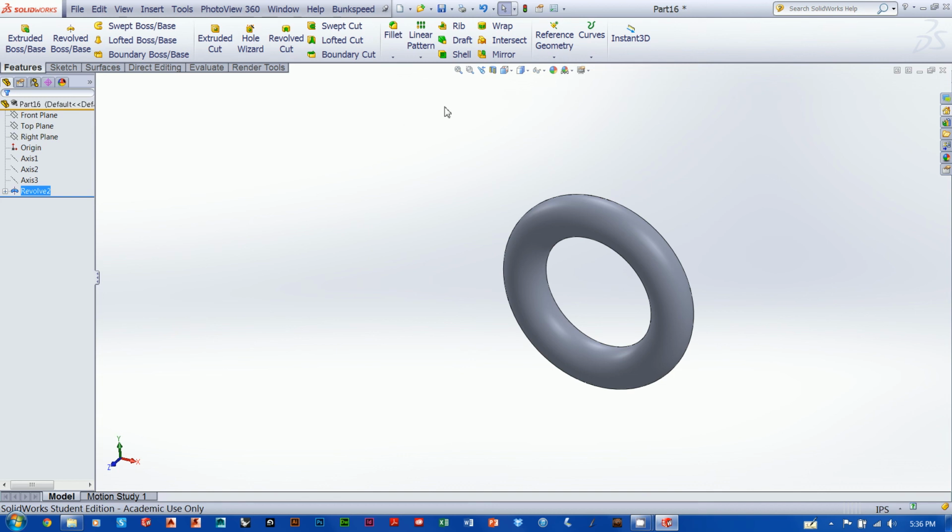So there you go. So that's why it's good to have a set of axes ready to go, and this is how to create a custom template so that once you make those 3 axes, you'll have them ready to go at any point. So there you go, guys. Everybody make your own template with all 3 axes ready to go. You can also click on them and rename them if it helps. But as you can see, just hovering over each one of them will show it in 3D space. So you should be able to get yourself off and running with all sorts of revolves.